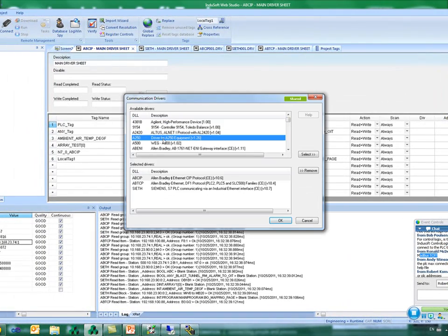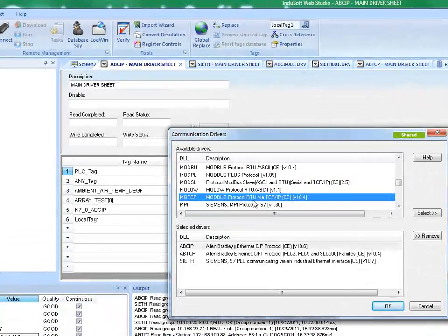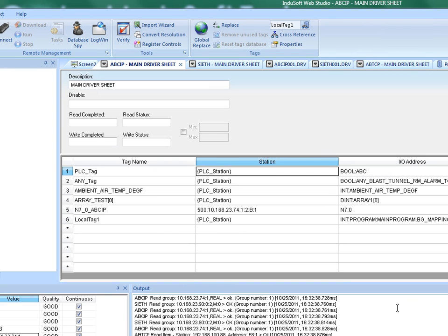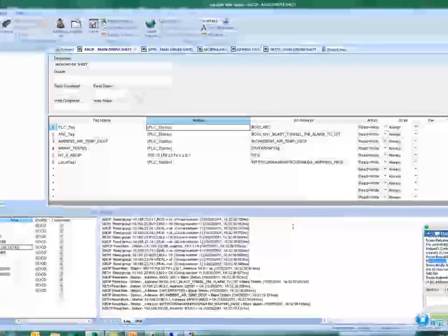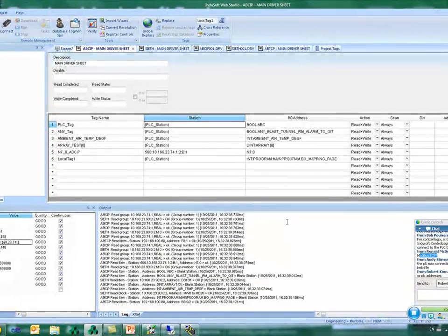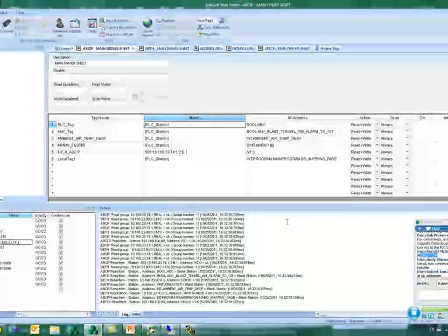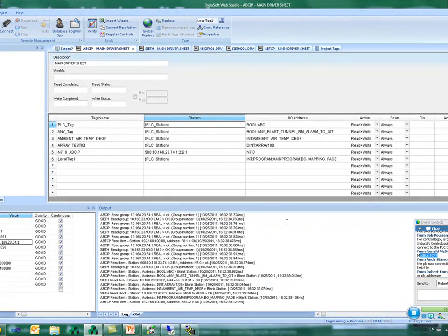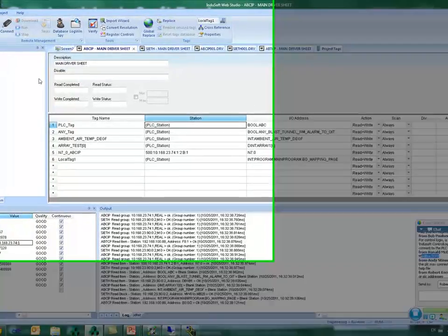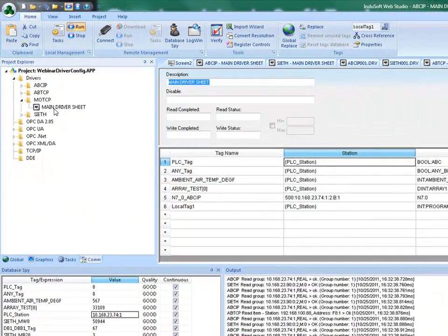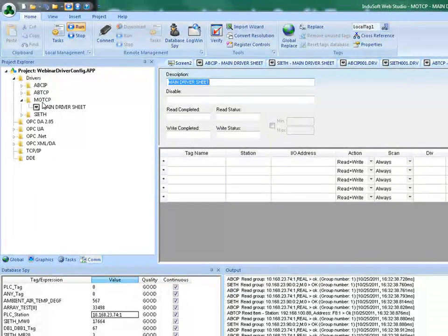That one is a native Modbus TCP. It's different than the encapsulation that I was showing before. The encapsulation is more if you want to have a serial to Ethernet converter. Usually you use that with RTUs, radio communications, where the PLC doesn't have Ethernet capabilities, has serial only. So you put that converter going to the serial port on the PLC at one end and the Ethernet at the other end. For PLCs that have Ethernet capabilities, you can use this driver called MODTCP.